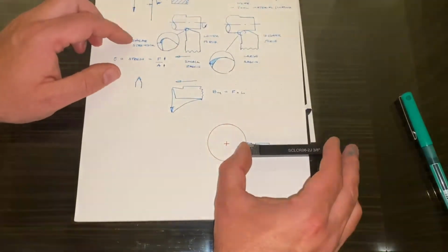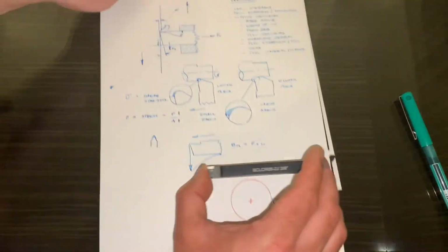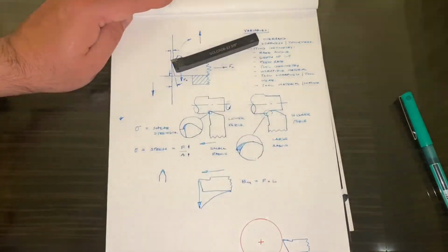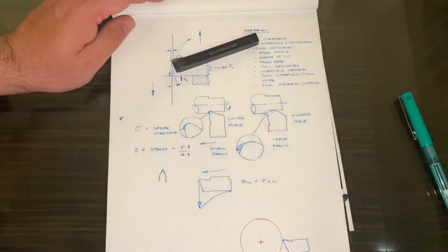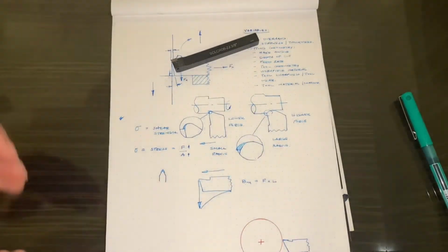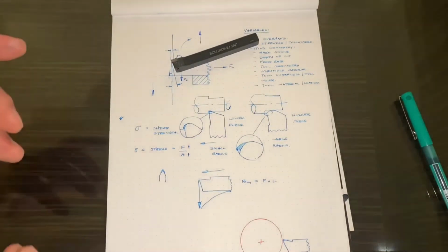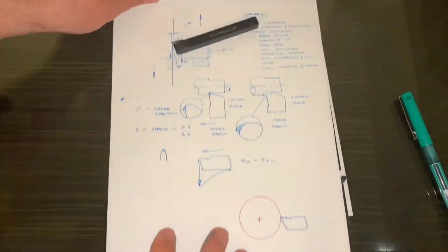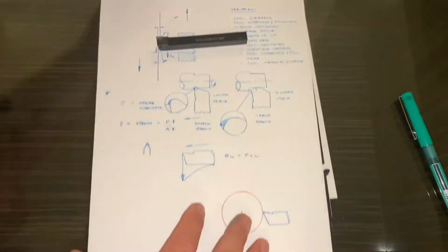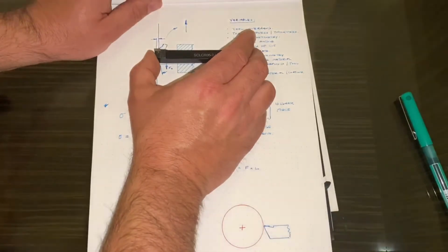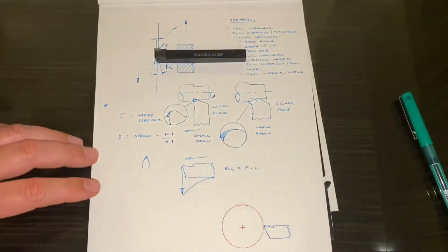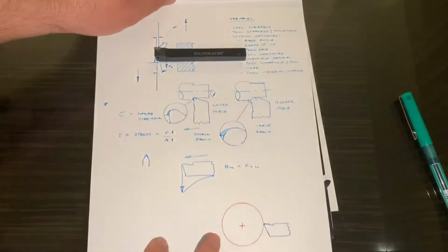When the tool is too low, we have the opposite. That's the equivalent of tilting the tool that way. And the result is we diminish our rake angle, and now we're going towards negative rake. And then that diminishes our machining efficiency. So what we want to do is keep our tool exactly normal or square, perpendicular to the local normal on a round piece of material.